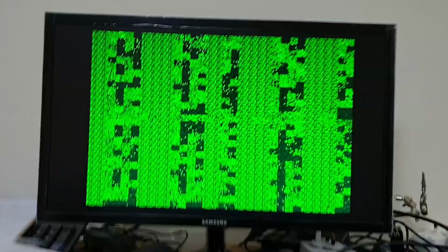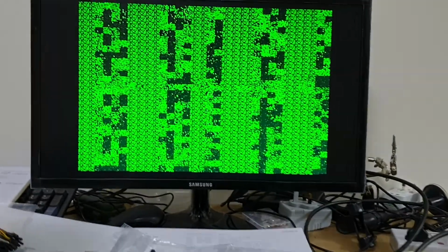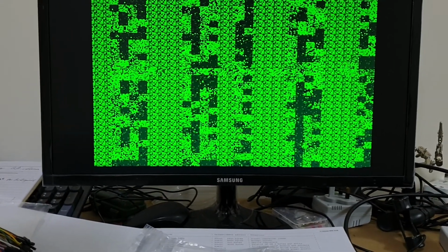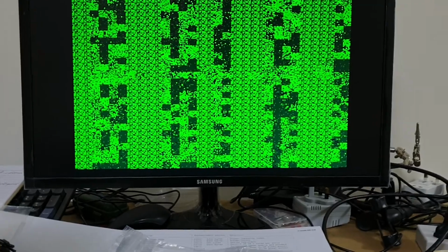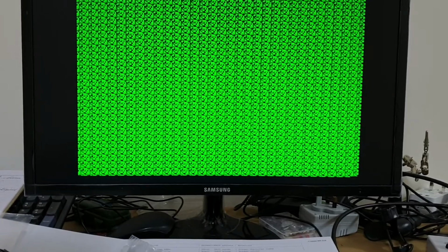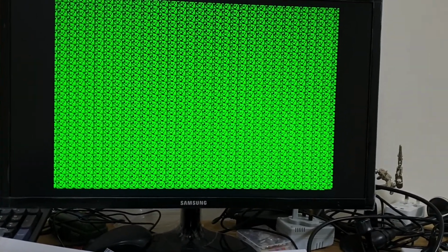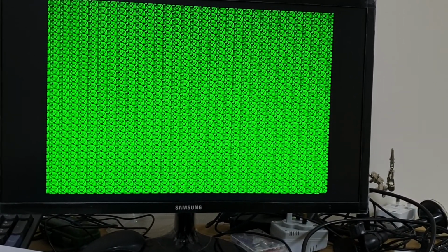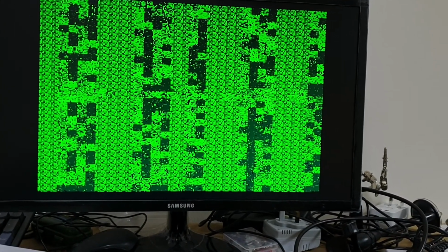Because at the moment, if I try and write to the screen memory, for example, while the screen is being displayed as it's tracing down, and this is what we get on the screen, is that we get bus contention, and obviously this is probably the character 2FF, the character 3FF, probably, because that's basically bus contention, and that's probably coming out logic high.